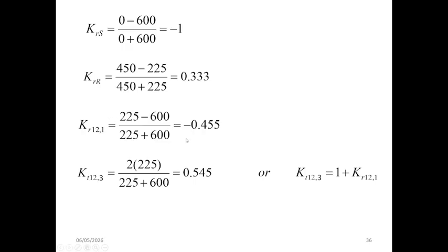All right. This slide presents the calculation of reflection and transmission coefficients at different points along a transmission line when a traveling wave encounters impedance discontinuities. So the reflection coefficient is determined using the standard formula Z2 minus Z1 over Z2 plus Z1, which compares the impedance before and after the junction.